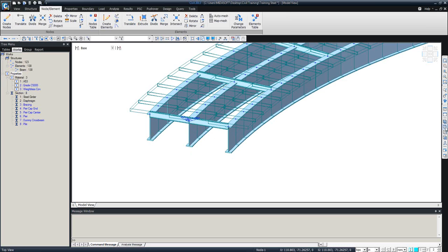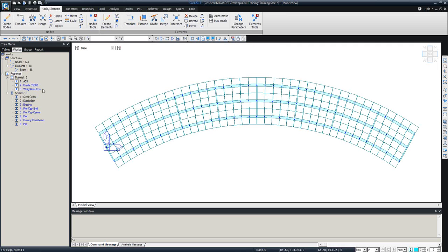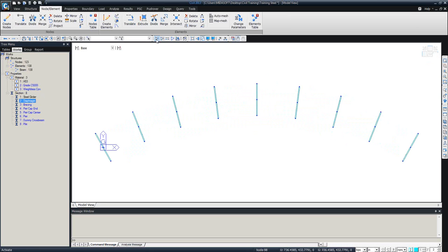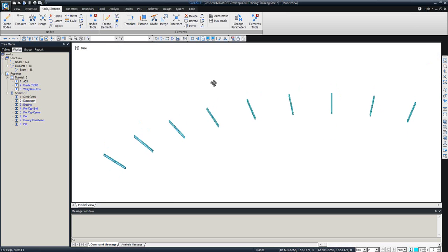So what I do, I go to the top view again, and this time I want to select the girders at the diaphragm locations. I double click on them, and then these will be highlighted, and I say select only. All right, so I got them here. I can select them all by clicking this option, and I want to create the nodes downward by 76.8 inches.